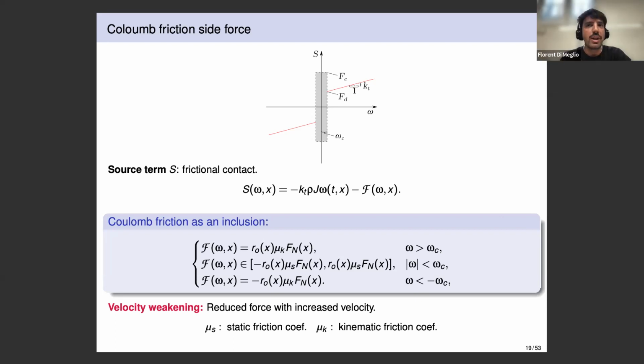Yeah, no problem. One thing about the use of observers is that you can make up for some model mismatch thanks to the fact that you're constantly feeding measurements to the system, right? But can you use Laplace transform on nonlinear equations? No, you cannot, because you have nonlinear equations when you have mechanical friction. You end up with an absolute value. What we do is we linearize the equation just to design the way we inject the measurement, but then we inject the measurement on the nonlinear equation.